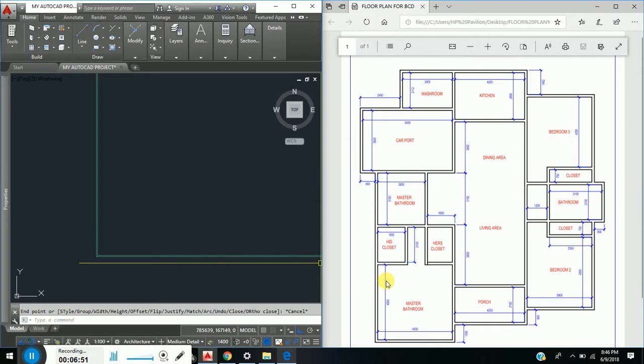Now, to populate the remainder of the building, what I'm going to be doing is to offset walls. One of the things we have to notice, however, is that whenever we offset a wall, and the dimension we are offsetting is an in-to-in measurement as indicated here, it is important that we remember to add back one wall thickness to that dimension, because AutoCAD will be measuring from the outside of the wall to the inside of the wall. So what we have to do is add back one wall thickness to its dimensions. Alright, so here we go.